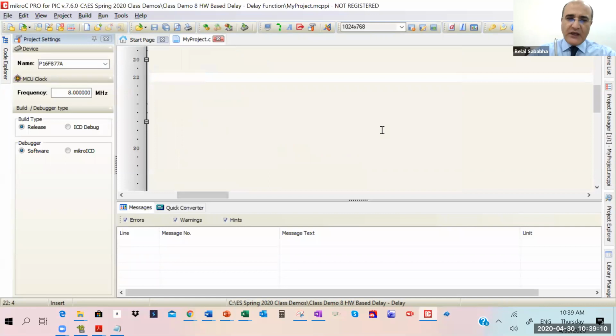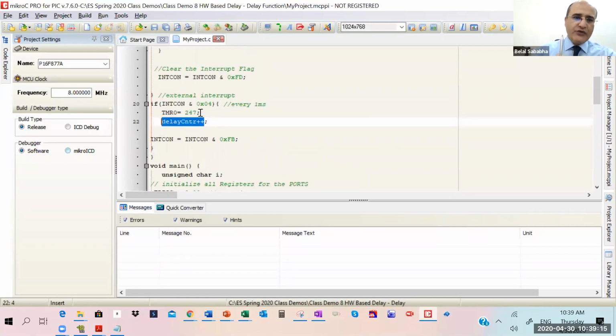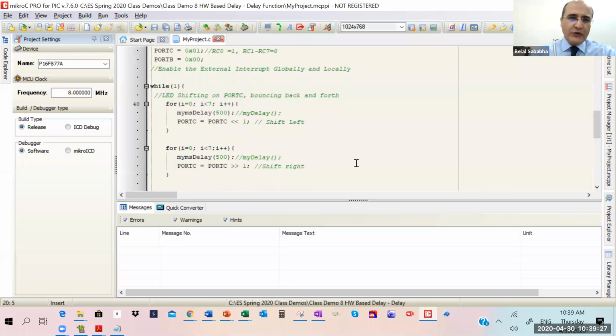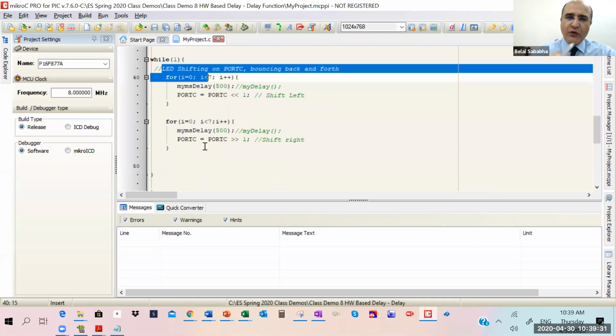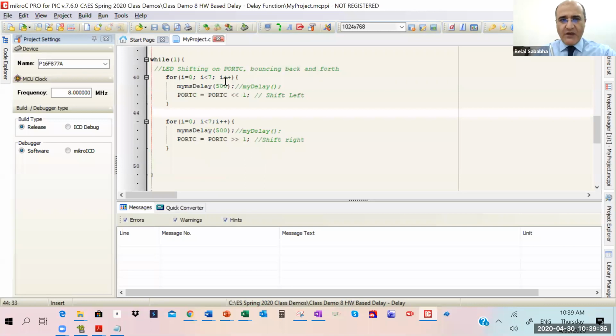Today, this is a periodic interrupt. Anyways, you come here every 1 millisecond, right? And increment a counter. This is periodic. However, we still relied on the main loop here, the infinite loop inside the main function, to do our core business, which is shifting the LEDs, if you remember.